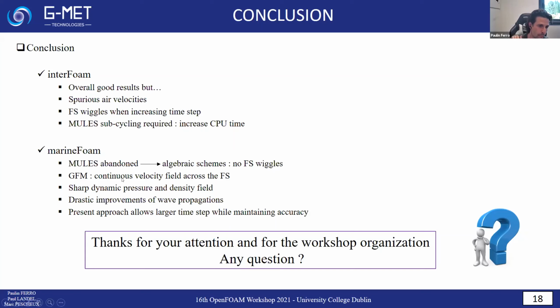On the other hand, with MarineFOAM, we abandon MULES in favor of algebraic schemes. So there are no free surface wiggles, and the Ghost Fluid Method treatment allows us to capture a continuous velocity field across the free surface. Also, as a result of the Ghost Fluid Method, we obtain a sharp dynamic pressure and density field at the transition. This is very interesting, and it drastically improves the wave propagation simulation. Finally, the present approach allows us to use a larger time step while maintaining accuracy.